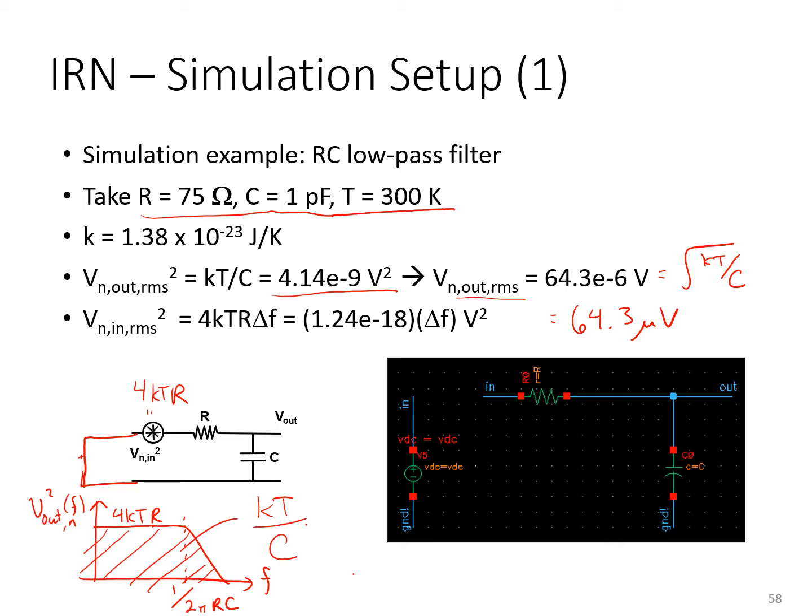Now, if we want to talk about the circuit's input-referred noise, that's pretty straightforward because there's only one device contributing noise, and the thermal noise of the resistor is essentially already input-referred. It's the only noise source, and it appears right at the input.